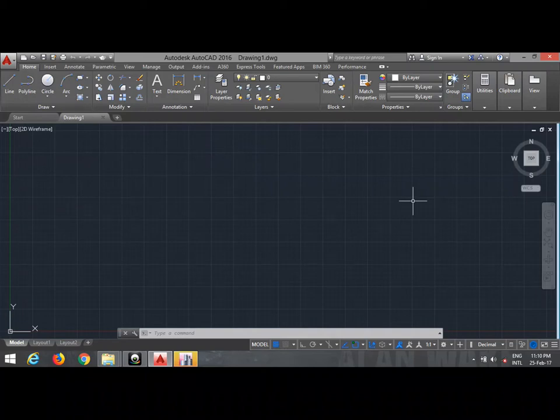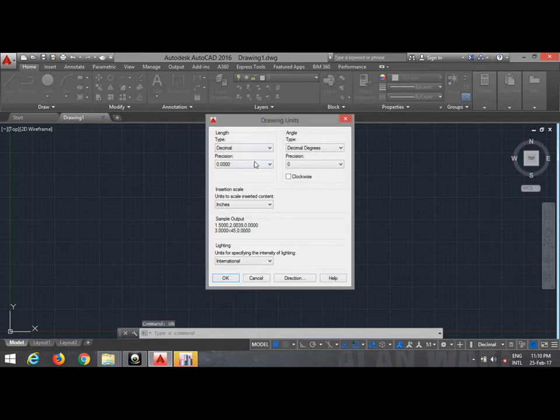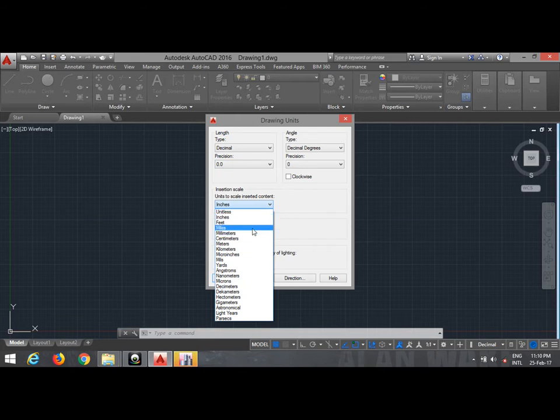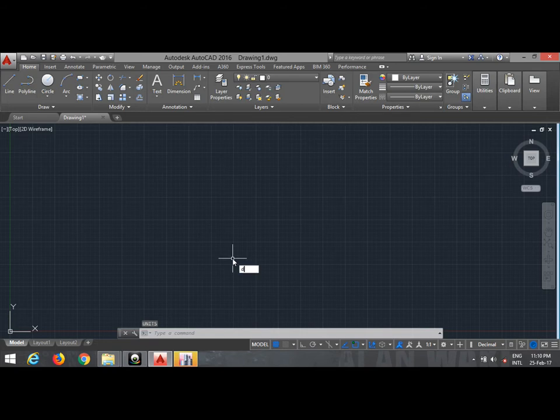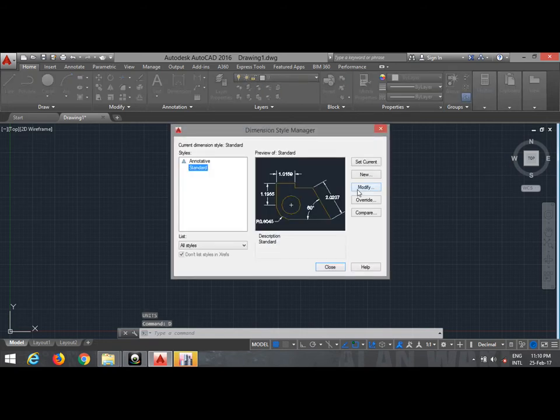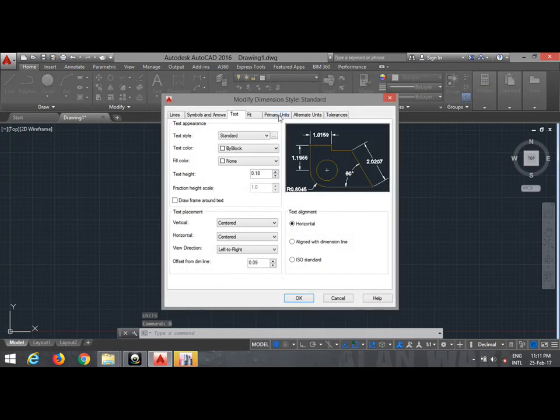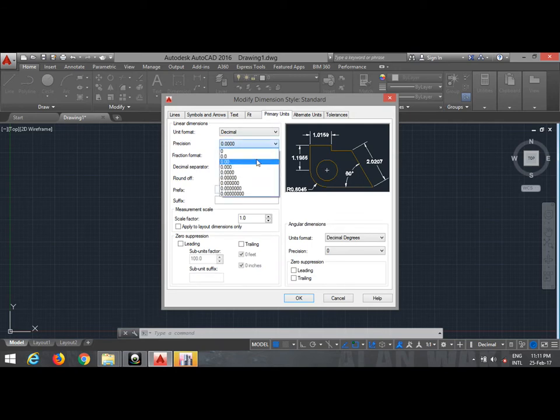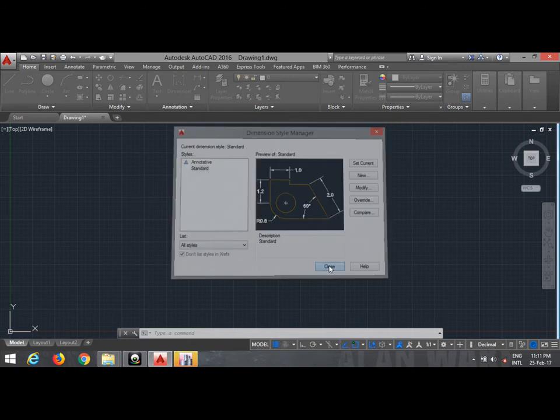In this video, we'll learn how to make circular beams in ETABS. First, we want to make a plan in AutoCAD. First, set the units to meters and dimensions. It should be in decimals. So take a precision of 0.0, close.